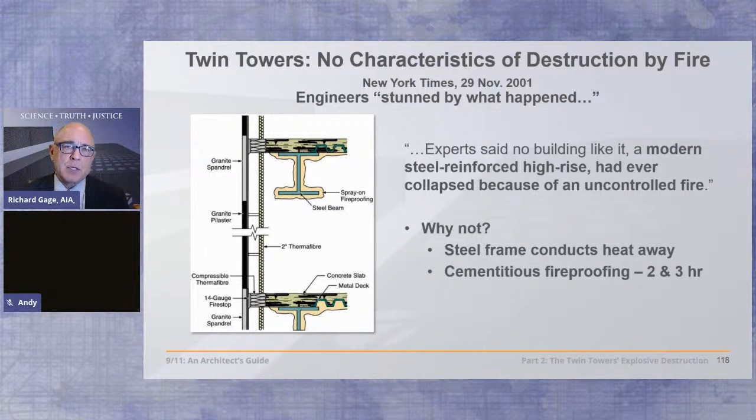So we put cementitious fireproofing on our steel frame structures. And that's really important. This is 2 and 3 hour fire protection. That means that the fire has to burn more than 2 hours on the columns, on the beams, and then more than 3 hours on the columns.